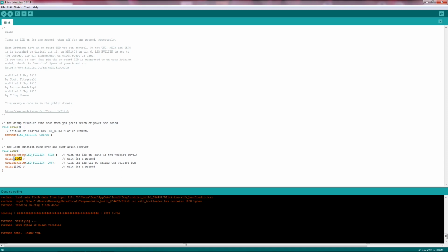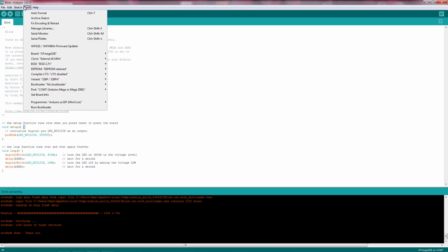And the result is that this delay here, which was supposed to be 1,000 milliseconds, is 1,000 times those wrongly calculated milliseconds, which are now twice as long, because they were calculated for 16 million operations per second, but the thing is running at half the speed. It's running at half the speed, it means it waits twice the time. And that's the reason for this. This is very important when you switch microcontrollers, or even in general, you're playing around for some reason, you change this. It's very important that what you have selected here matches the speed of the crystal you have in there.